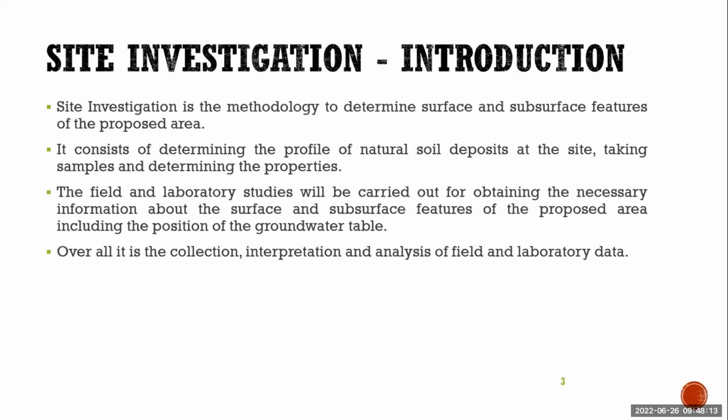Or maybe there was a lake in this particular region, and now it can be dry. If the deposits happened due to the lake, small fine grains will be deposited. That is called lacustrine deposit. Or it can be a wind deposit, which we call an aeolian deposit. So it can be any kind of deposit, deposited by transported material, or it can be native soil.